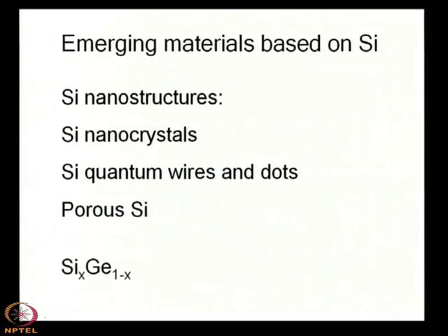And for this silicon germanium material I have one thing to add. You know that in compound semiconductors, and we shall discuss this in the next class, like gallium arsenide or indium phosphide, the processing technology is not very matured like silicon. Annealing, oxidation, implantation, diffusion, lithography, these are very standard techniques for silicon only. You cannot use those processing technologies, or handle large wafers for compound semiconductors like silicon, where you can handle very large wafers.